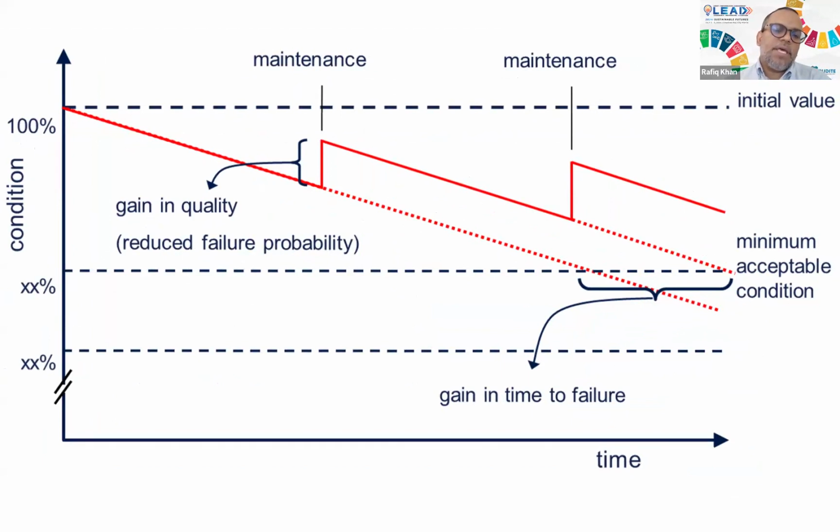A solar panel degrades by about 1 to 2% in a year, based on the construction of the solar panel and its chemistry. But there are other factors that also affect the performance of a solar panel. Things like soiling, dust collection over a panel, can quite significantly affect the performance.